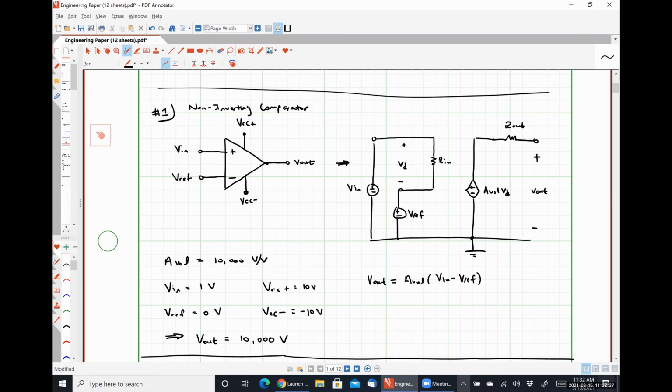Inverts the output. So to me, inversion implies a change in polarity. I could argue that in some sense it does, but I'm going to leave this output voltage positive polarity on top, negative polarity on bottom. What is literally the physical difference between these? Well, don't even get into how the circuit's going to behave. What physically changed? VN and VREF switch places.